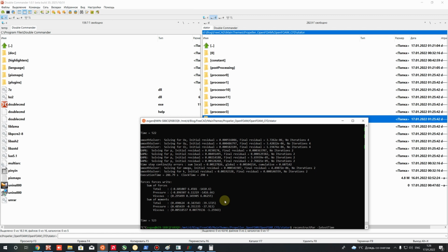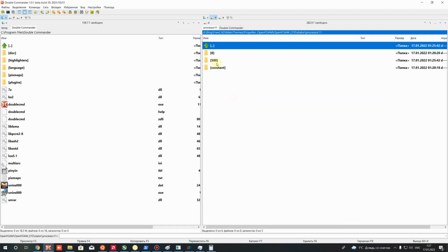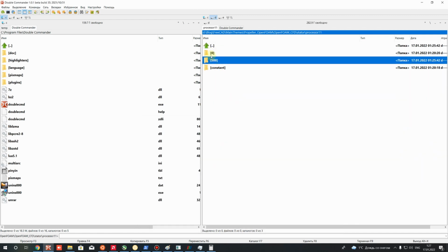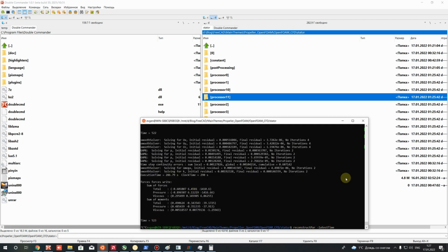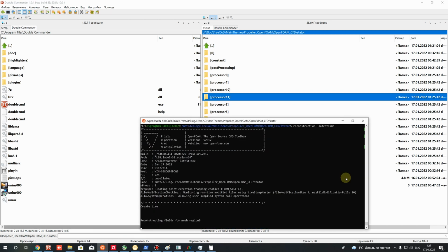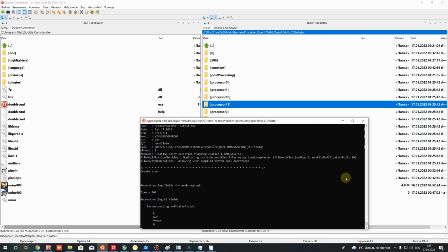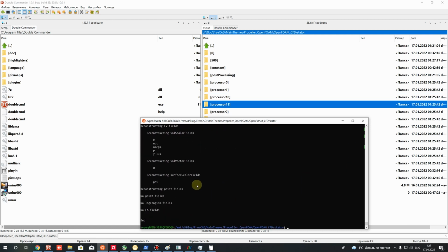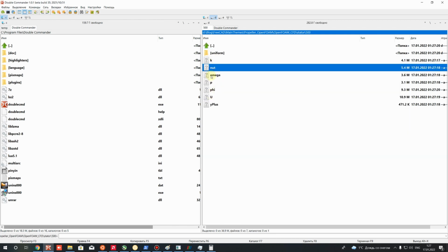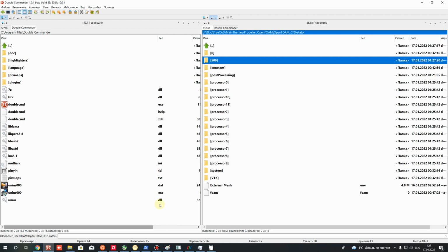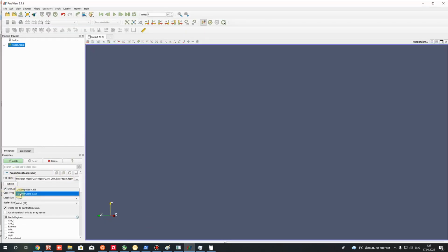It means that it will use the last time, because if you have, for example, several saved times, it will save all of them, but I use the latestTime tag, and you will get these 500 results of your fields in one file. Of course, you can open different types of cases.